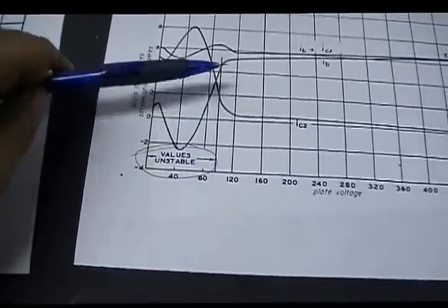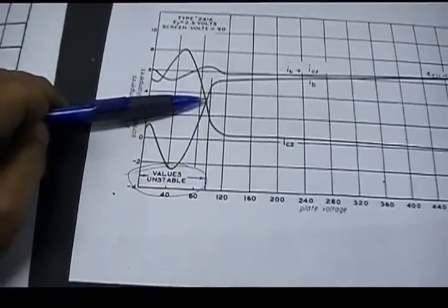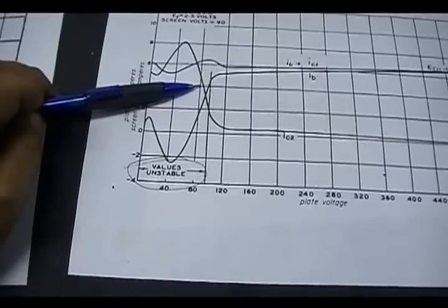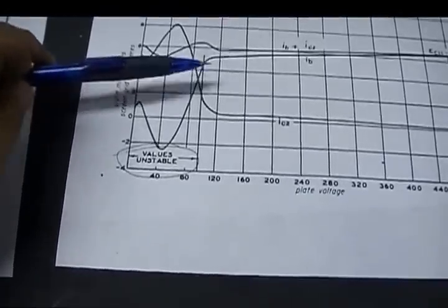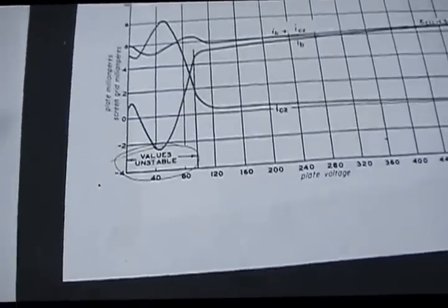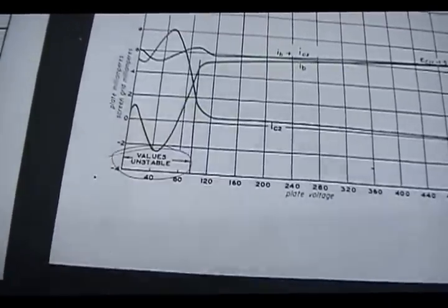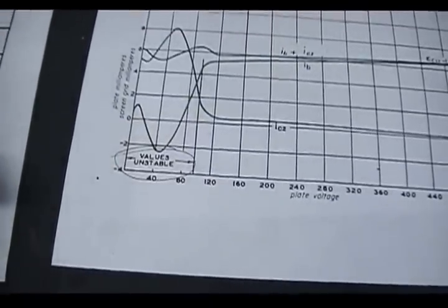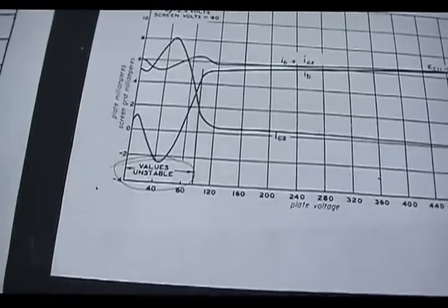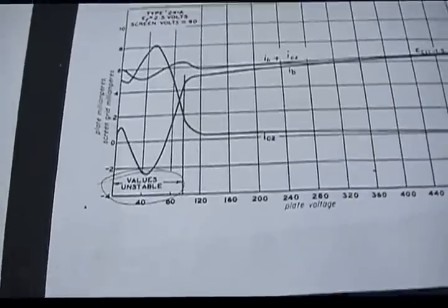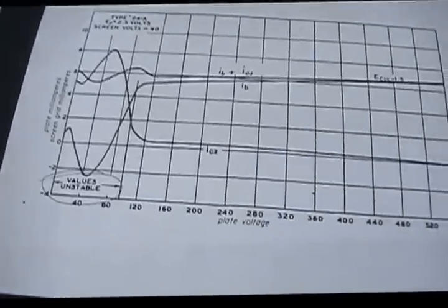And the problem is when this thing's acting as a voltage amplifier, the plate will drop below that at times on the swing of the AC signal. I got a problem. Now you can hook these up to an AC transformer, have a secondary step up transformer, get 200-300 volts. That wouldn't be a problem. Batteries, a lot more difficult.